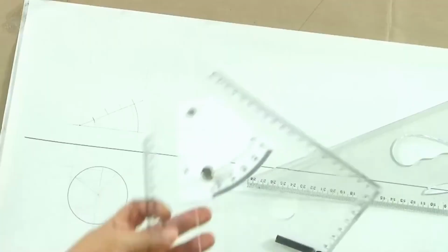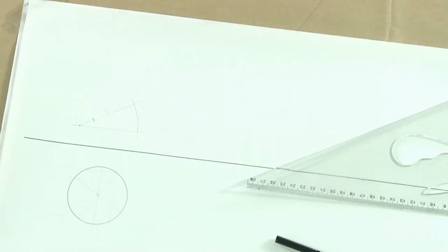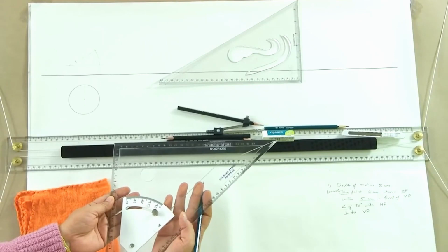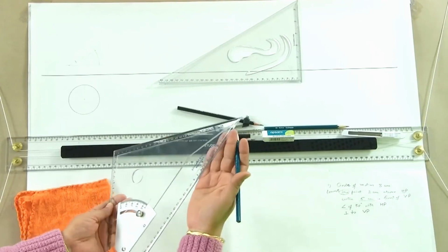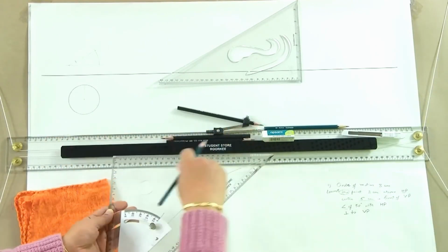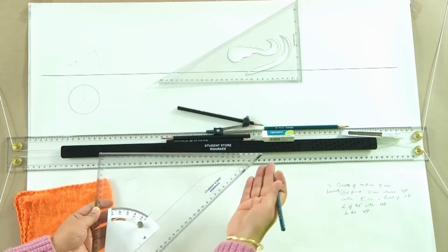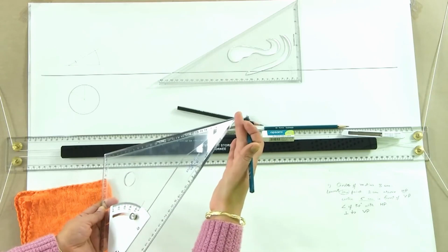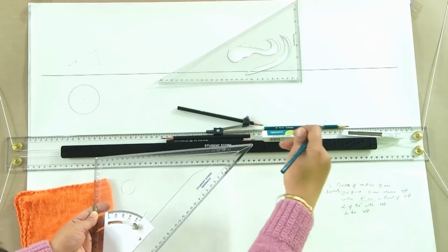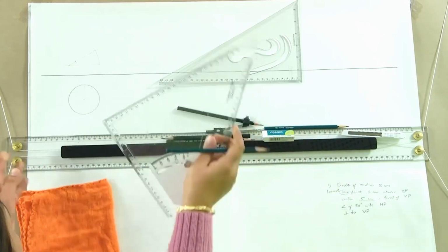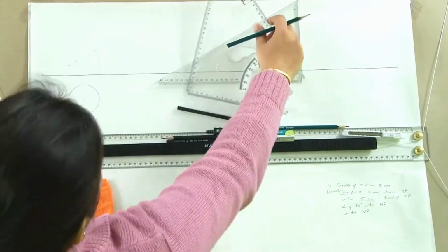When we are inclining this plane, which was parallel to HP, the points move, but their horizontal projections remain the same. So their vertical projections change. A point which was here has gone up there, but horizontally it still falls on the same line, which is the principle we have employed here.